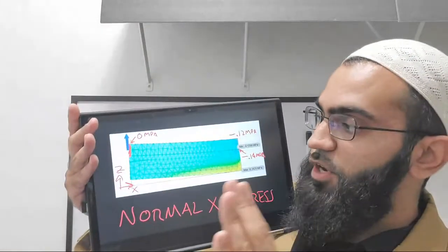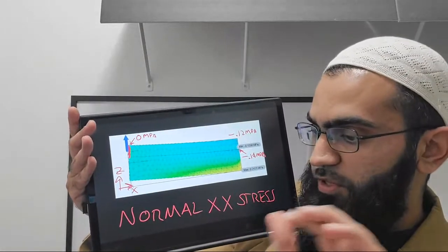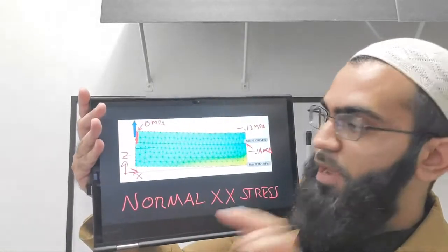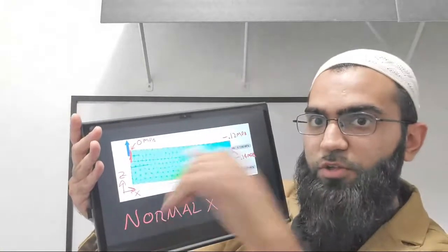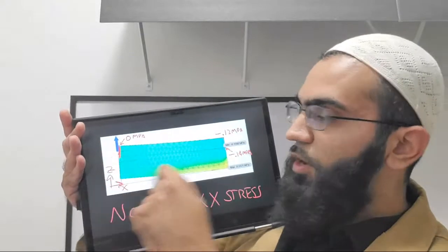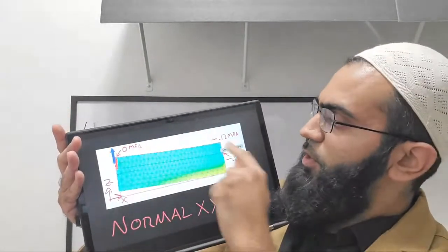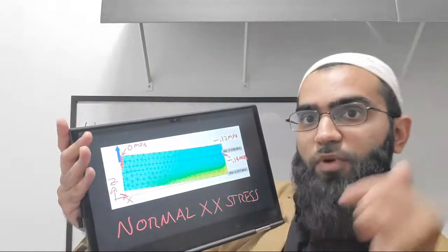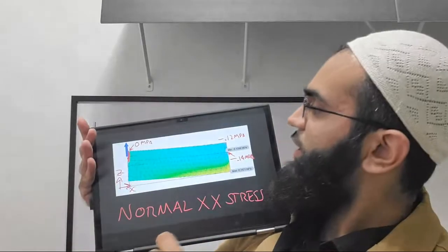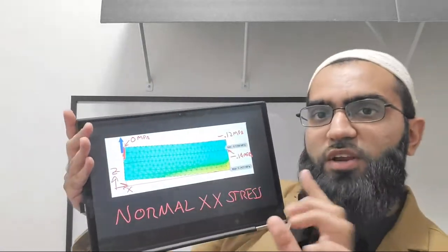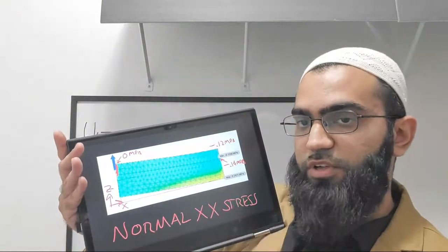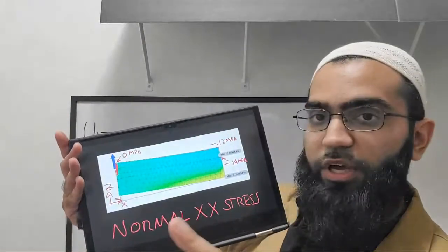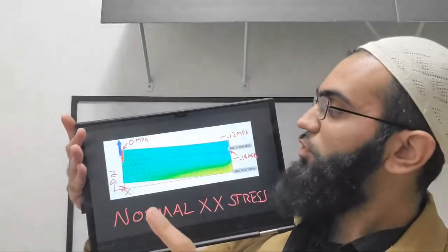We're making an assumption here, that the voltage generated on the piezo is mainly dominated by the forces developed in the length direction, because as you push down on the piezo, it's going to be stretching in the direction of curvature developed from the flexural force applied. So we want to find the average stress, and that's going to be quite critical, to determine the average stress of the device in order to calculate voltages.